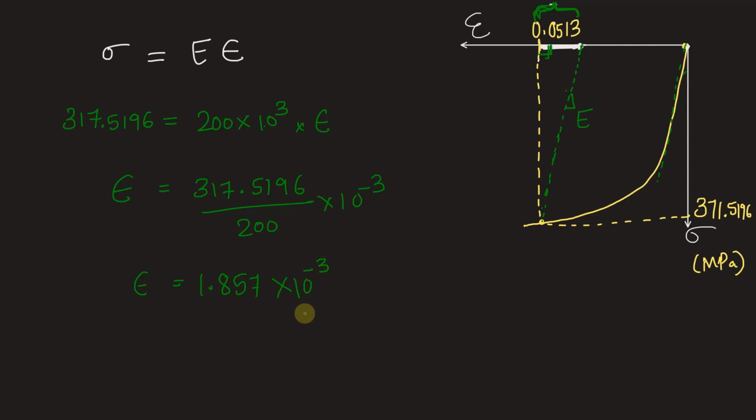So we can find out how much has the length changed for this elastic recovery. Now this elastic recovery is going towards the positive side, opposite direction to the compression, and because this is the elongation of thickness, therefore, we can equate this to change in thickness when the elastic recovery takes place divided by the initial thickness.